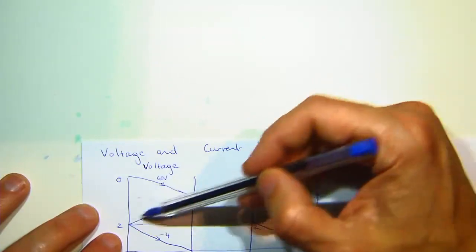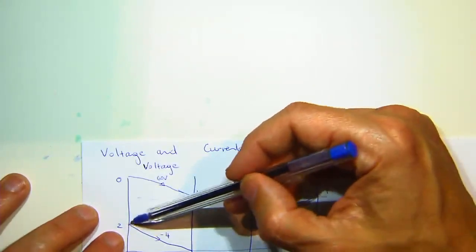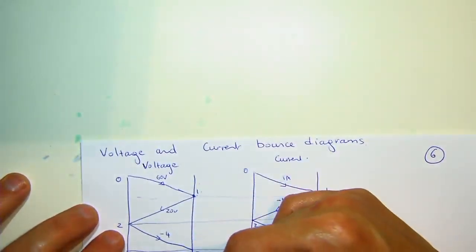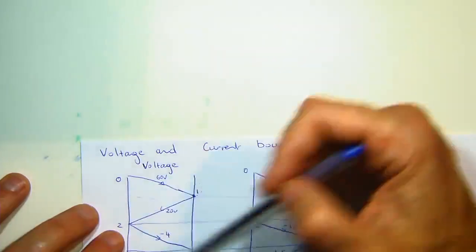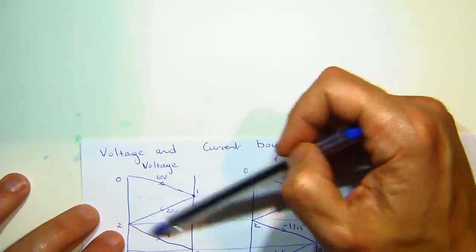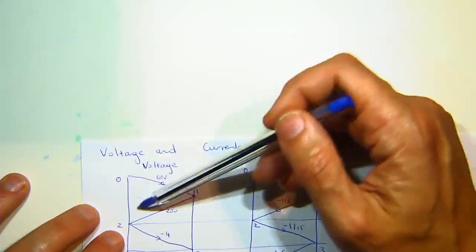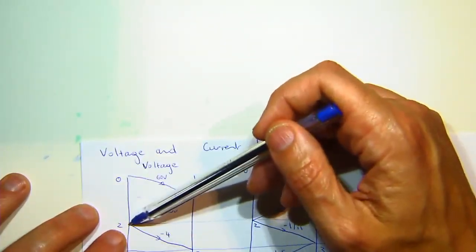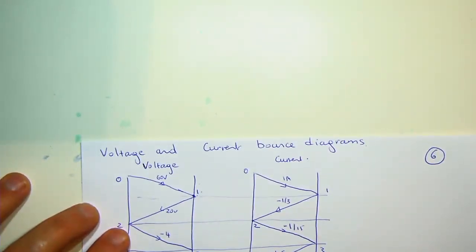Just before it hits the source, we expect this voltage to be 80, right? But we know that the reflection coefficient for the line to the generator is -1/5. So therefore, the reflected voltage is going to be -4 volts. So the voltage is going to be 80 minus 4, so it's going to be 76 volts here, right? So what we can do is we can actually start drawing these diagrams.